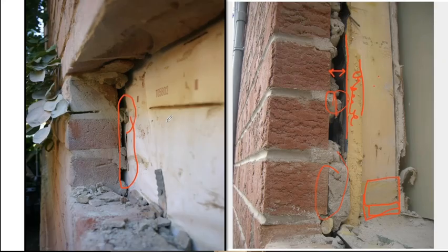The picture on the left actually is a building with problems, and this is a construction photo on the right. On the left-hand side is an inspection opening. We've taken a saw, we've had a mason cut open the building, and you can see the gap here is quite small. But that said, water will run through that gap faster than you can pour a pitcher of water.